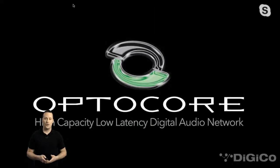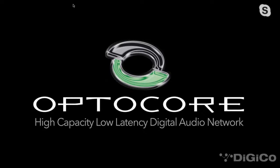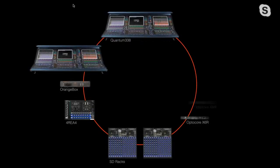All right, now on to OptiCore. I told you a little bit about this earlier, but OptiCore is a high-capacity, low-latency digital audio network. We have actually been integrating OptiCore for a long time now, and there's a whole lot you can do with this. First of all, the quick overview: OptiCore is a fiber ring-based network. So the idea here is that we start adding devices and we connect cables between each of the devices in a ring or a loop topology.